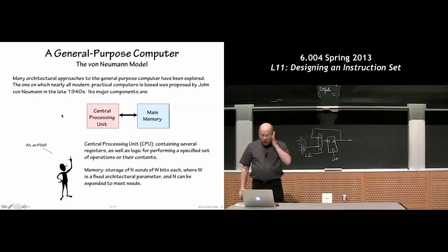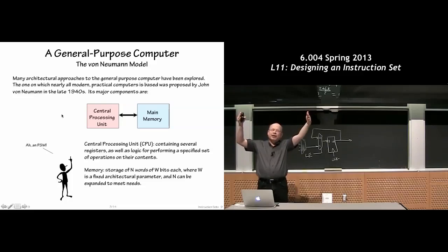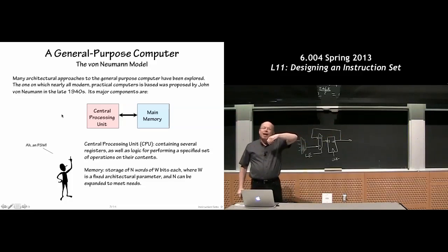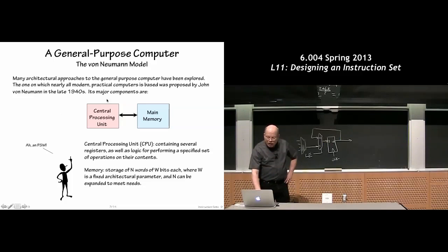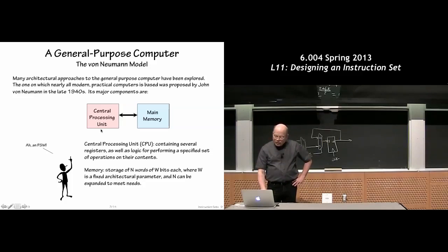We're going to add a main memory, and think of it as an array of locations, and each memory location will have a certain number of bits of information in it. So we're going to send an address to the memory to tell it which location we want, and it will return to us all the bits in that particular memory word, that particular element of the memory array. Okay, and the idea is that even though we have some small finite scratch memory inside the central processing unit, conceptually this can grow quite large.